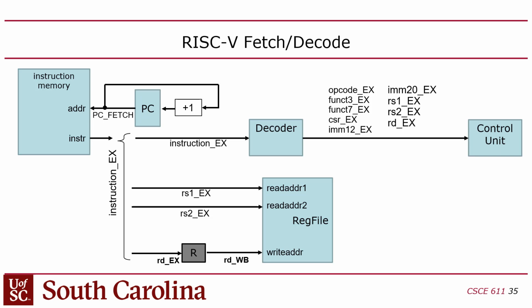Right? Which means you're now going to have 2 names in SystemVerilog referring to the same 7 bits. Which seems wasteful, but it doesn't cost you anything in terms of the hardware. You're just creating an alias. So he did that through the decoder. He called this thing the decoder, but it's not really accurate. It's not really decoding anything. It's just renaming signals.